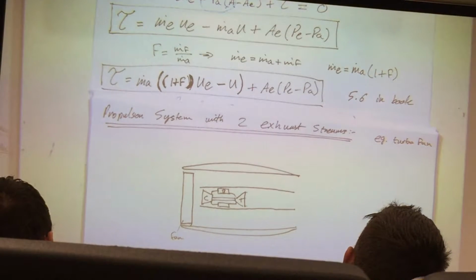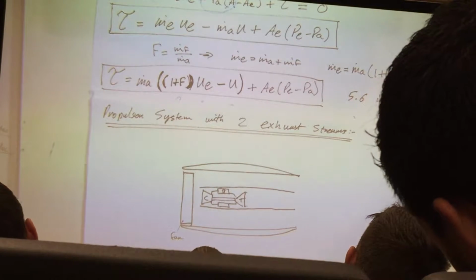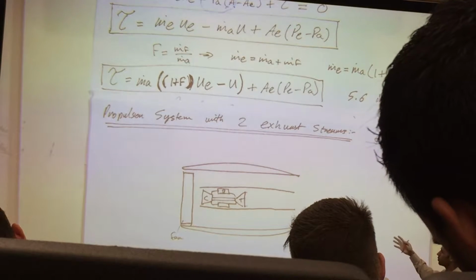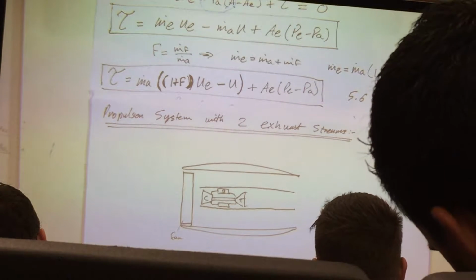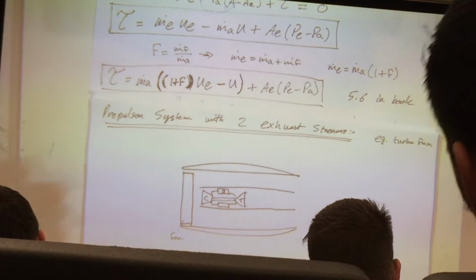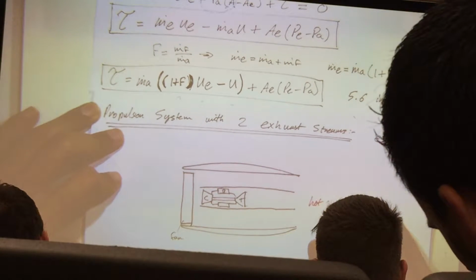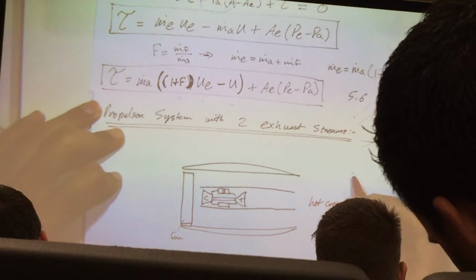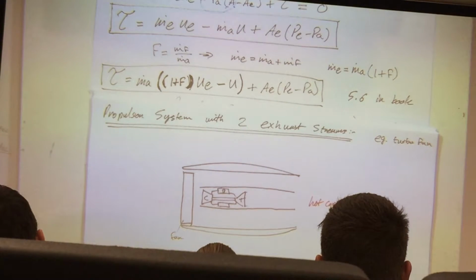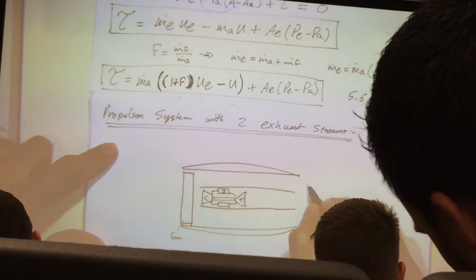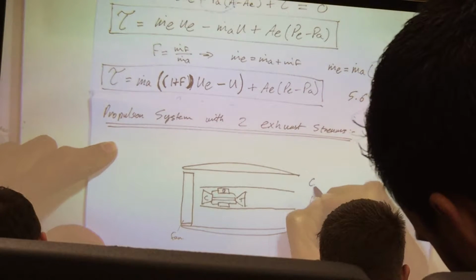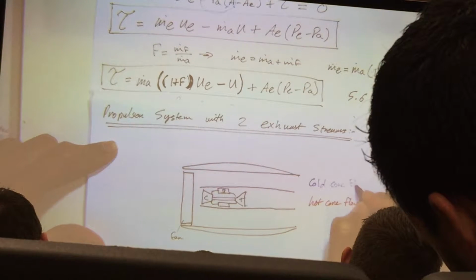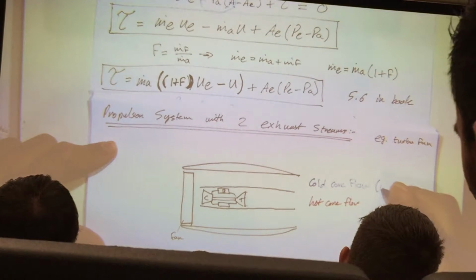Okay, so we want to isolate this by two streams. So it's the same thing that we just did with the turbojet. The difference is now I have to bookkeep my mass and momentum for all the different streams that I have. But I have two main streams. I have a hot flow, which I should have written inside, and a cold flow core. No combustion.